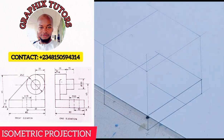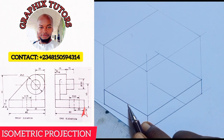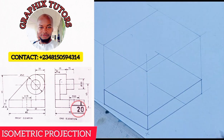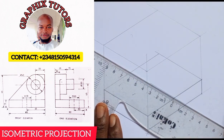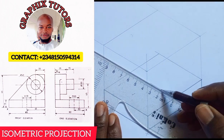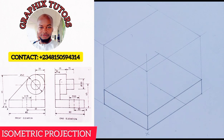Hope you can see that. And on that line, it's telling me that from the end elevation, which is at least the end elevation looking from this side, I'm going to measure 20. So either I measure 20 here or I measure 20 on this line. I'm still saying the same thing. So I measure 20 on this line here. So 0 towards 20. This 20 here. And I will now rule my line across that point.